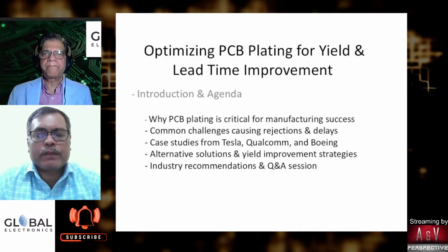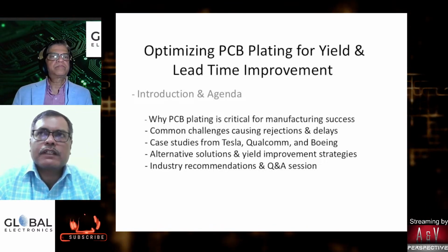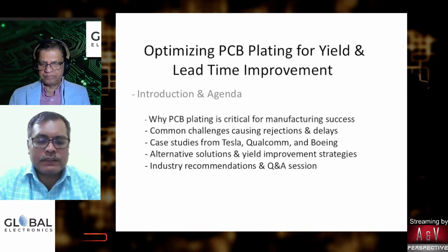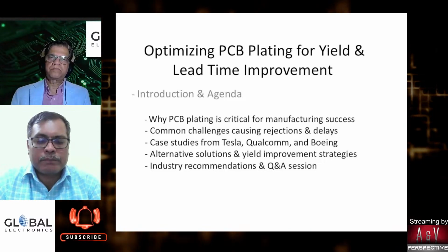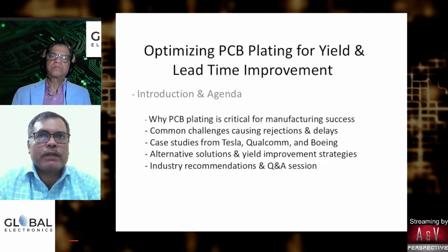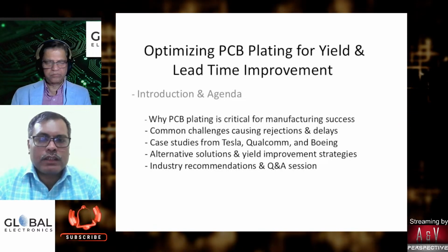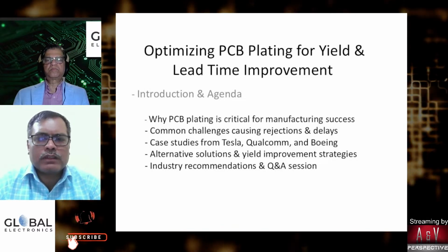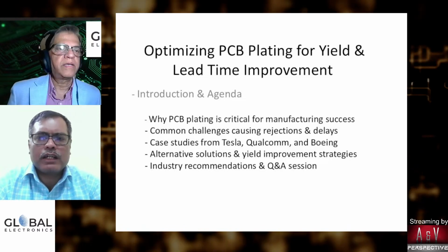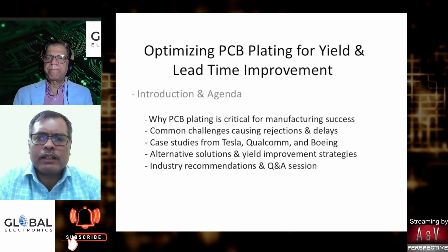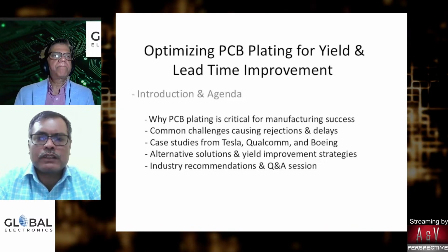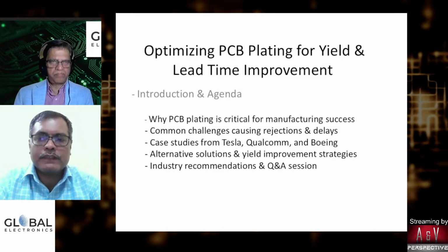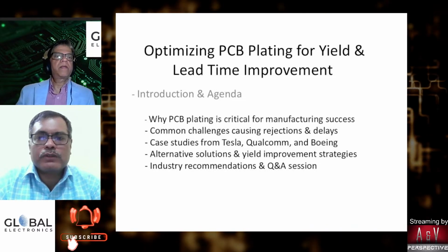In PCB manufacturing, based on our experience of dealing with our PCB manufacturers, three important things come into the picture: the minimum drill dia, the PTH electroless copper plating facilities, and copper plating. These three things play a very important role. When you are talking about PCB plating, I would like to come to the presentation part, where we dealt in detail with the PCB plating issues that we have experienced in the recent past. So you can go to the second slide.